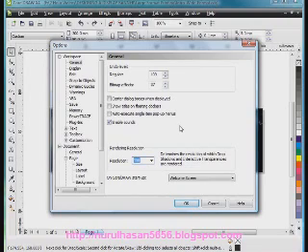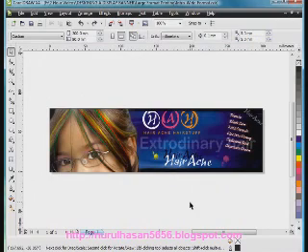You're going to be a long way away from a banner that size. Therefore, the resolution is most likely going to be printed somewhere between 60 and 100 dpi. So the rendering resolution, which affects drop shadows and transparencies, and remember we've got transparencies, you want to set to something between 50 and 100. So maybe 75 dpi. Click OK, and that will make a huge difference to the file size for my printer to work with.